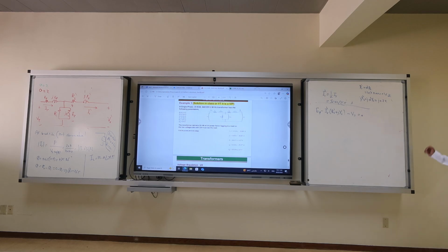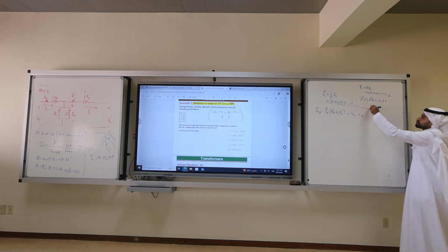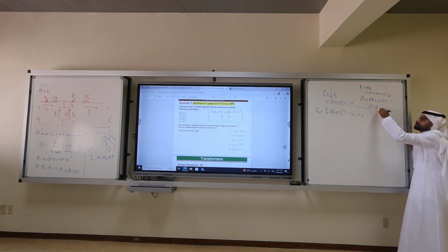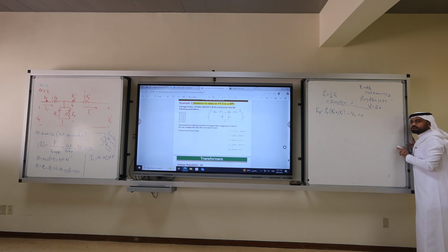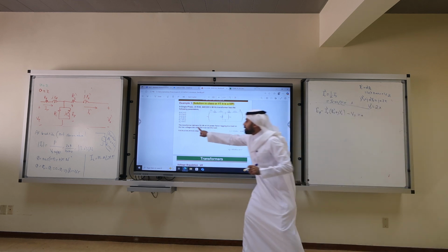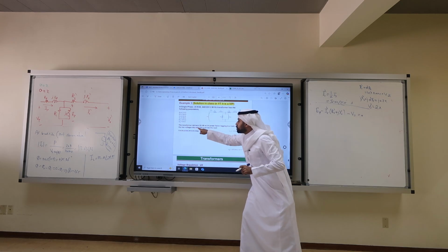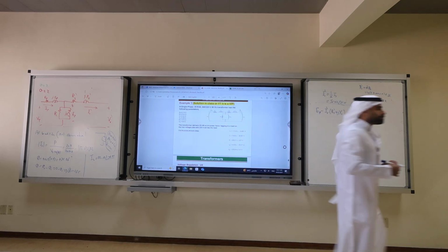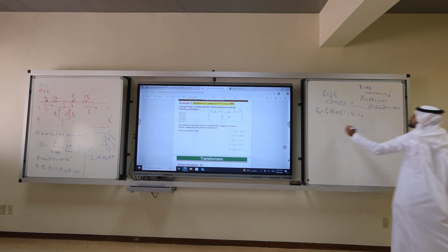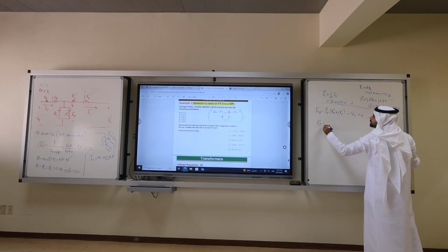What is Vs prime? I asked this question before. What is Vs prime? A times Vs. Okay, what is A? 2. What is Vs? From the problem, low voltage side with 220. So Vs prime is 440 volts. So calculate with me Ep.